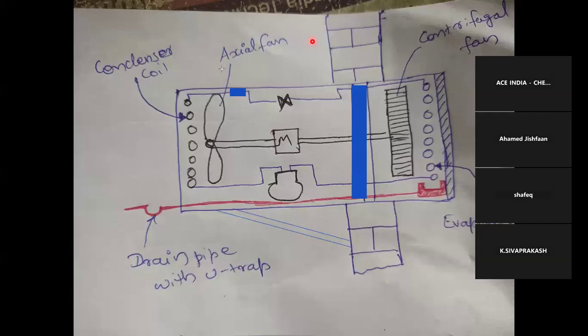So the point is very simple. The fan is boosting the heat transfer. That is the sole purpose of a fan. All right. Is it clear, guys? If you are not installing a fan on the condenser side, there shouldn't be a problem, but it takes more time to reach the subcooling temperature or the subcooling process. Or we can say it takes more time to reach that critical point to get converted, isn't it? Am I right? So that's why we need an axial fan. This axial fan can boost up the process, and the refrigeration effect cannot be hindered if there is an axial fan.